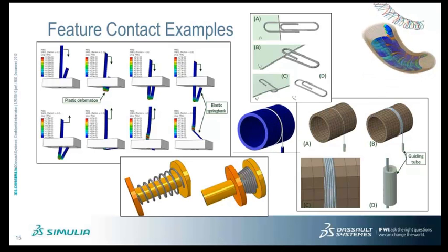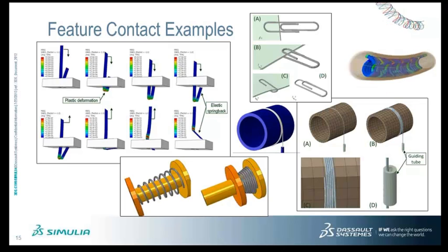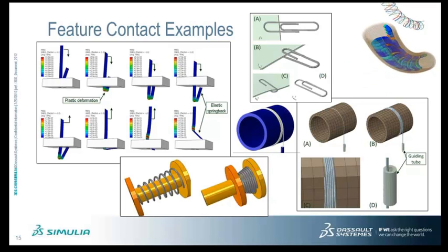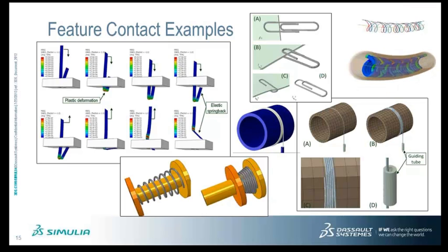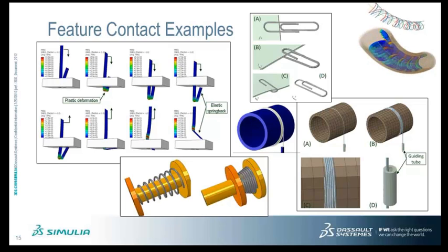The one on the bottom is an earlier analysis where they had to model the interior coil using solid elements because we didn't support the contact with the beams. But now the analysis up top with the general contact with the beams, the same analysis can be done, but with a smaller dimensional model, still with very good fidelity, but at a much lower cost.